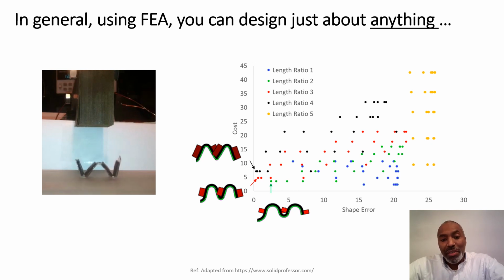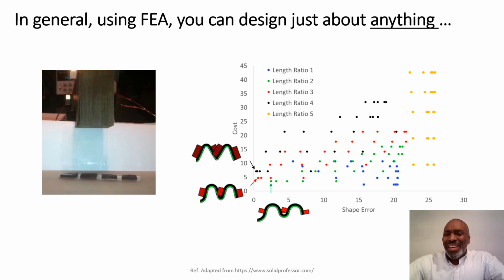Well, on the right, what you're seeing are finite element simulations of probably several dozen prototypes of that device when it's subjected to an electric field, right? So each of those data points, each of those points on that graph is a prototype of a different size, a different shape, different strength magnets that are attached to our little piece of rubber, different thicknesses of those magnets, different stiffnesses of that substrate, different thicknesses of that substrate, so all different design parameters that we've built into this. And what we do with our analysis is we look at it for shape error. How close does it get to the target shape, that accordion structure that we want,